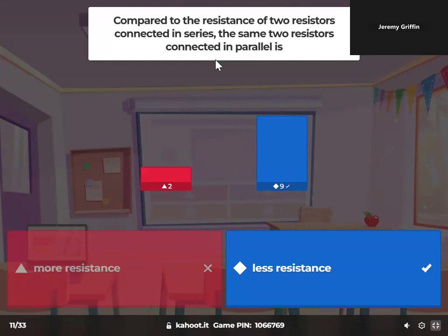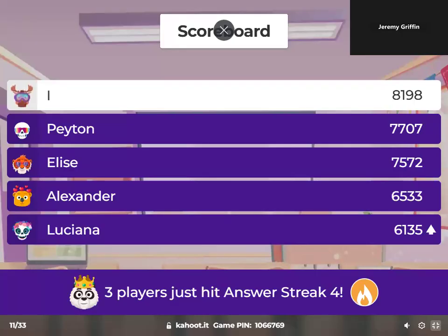100? And then 10 plus 10 is 20. What is 100 divided by 20? That's also 5, isn't it? Aha. Right. So in series, 10 and 10 is 20. In parallel, 10 and 10 is 5. Ooh. Right? You guys got that?